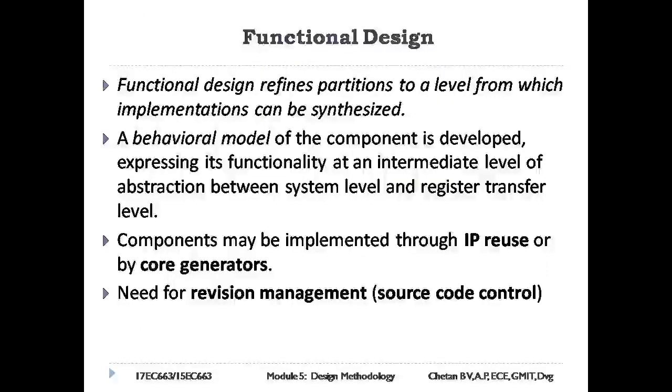Functional design. Functional design refines partitions to a level from which implementations can be synthesized. A behavioral model of the component is developed, expressing its functionality at an intermediate level of abstraction between system level and register transfer level. The components may be implemented through IP reuse or by core generators.